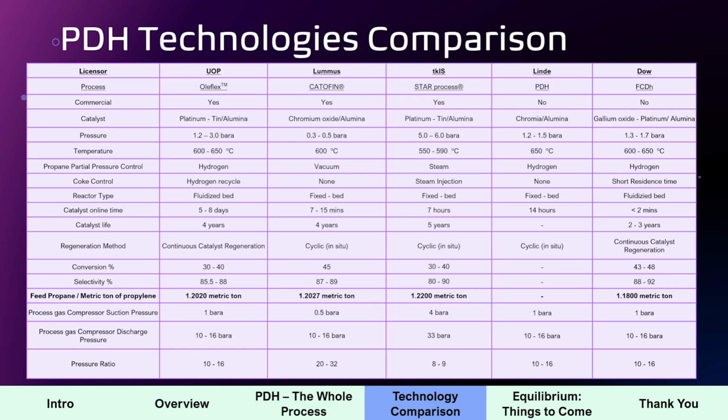Propane is basically dependent on natural gas price. Propylene has nothing to do with propane. It depends on crude oil, because it's mainly coming from that direction. So if propylene price goes down, your margins can very easily go into negative cash flow. So the economics of the process, whether it's operation cost or capital cost, is dependent on the difference between those two.